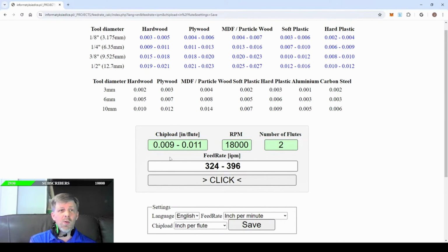So when we're clearing or we're just removing material, the finish and the quality is not important. But when you're doing a finishing pass, or when the surface or the quality of your cut matters, your step over should be really low, somewhere between 12 and 6%. A lot of people will say that 8% is the Goldilocks percentage, and that is true for some bits.